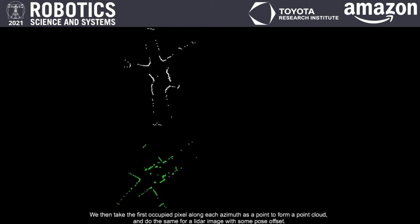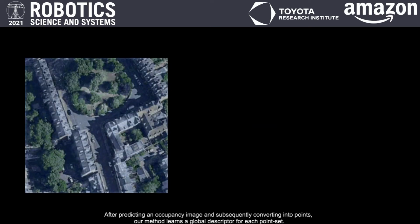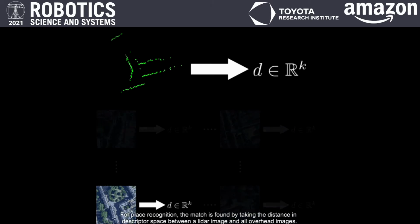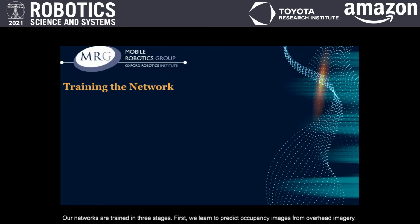We then take the first occupied pixel along each azimuth as a point to form a point cloud, and do the same for a LiDAR image with some pose offset. Our method learns the point cloud registration to compute the relative rotation and translation offsets between the overhead image and the LiDAR image. After predicting an occupancy image and subsequently converting into points, our method learns a global descriptor for each point set. For place recognition, the match is found by taking the distance in descriptor space between a LiDAR image and all overhead images. Our networks are trained in 3 stages.